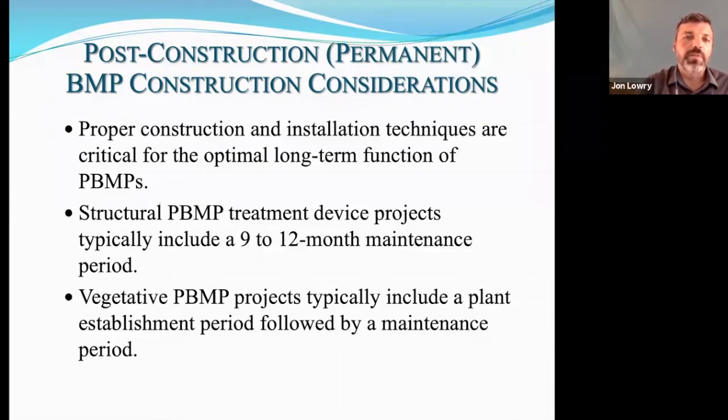For structural BMP treatment devices, we also typically include a 9 to 12 month maintenance period, so that the contractor that actually installed the device is responsible for maintaining that device. So it's important for you to know what the maintenance requirements are. And it's important for us to get that data from you so we can know how to best manage that device long-term.